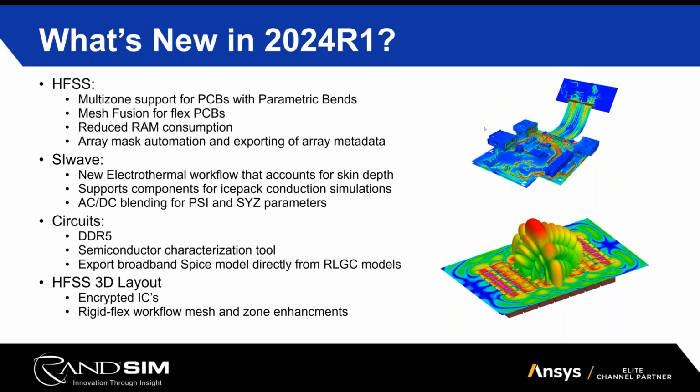You can utilize different regions, or layers, if you will, to then solve those individually, so that something that requires a really high fidelity, like inside of an IC or a section of a printed circuit board, can focus in that region and then let the rest of it be solved independently, and then HFSS will converge and stitch all of that together. So mesh fusion is a really beneficial process to help enable you in growing the scope of your simulation complexities.